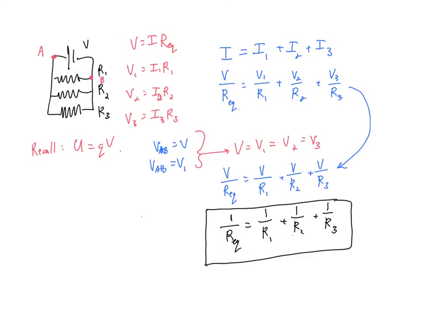The equivalent resistance, and that is the resistance which would go into an Ohm's law, like V equals I R equivalent, for a parallel circuit is the inverse of the sum of the inverses of the resistances. Okay, great. So these are the two basic ways you can combine resistors. Now, of course, you can have some series and some parallel circuits as well, but that's just individual parts being parallel and individual parts being series, and you can combine them in different ways. And I'm sure that you'll see some examples of this in your class or in the homework.